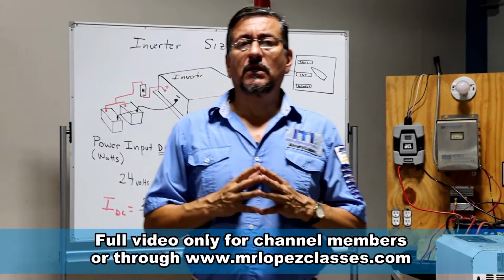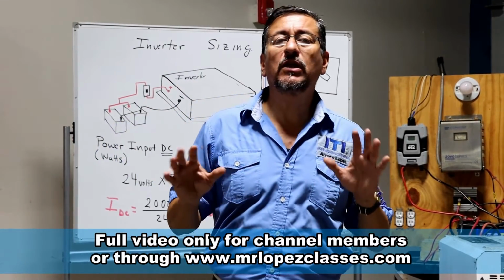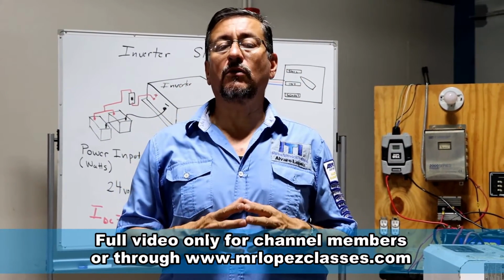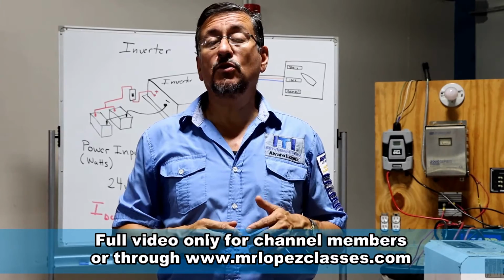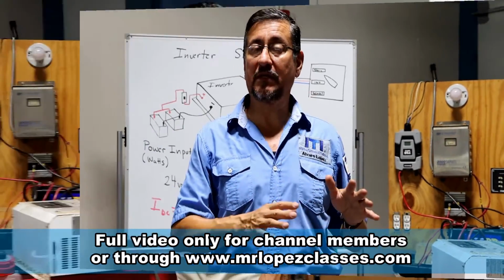For that reason, the power produced by the inverter is used only in emergency, and is used for some equipment, not for all the breakers in the AC panel. Why? Because if you use the power produced from the inverter for all the breakers, you need a lot of batteries to supply power for that equipment.